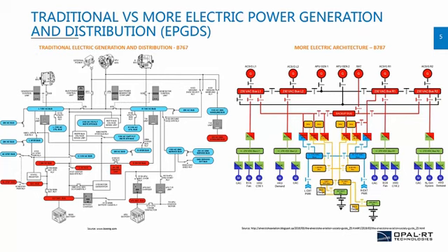As opposed to that, on a MoreElectric architecture, we see many more voltage levels involved, and much higher as well. So 230 volt AC bus plus or minus 270 volt DC bus in order to accommodate electric loads that will consume more power. And this is basically to control the losses on the wires on the network. We can also see in a MoreElectric architecture the usage of many more power converters that will feed those electric